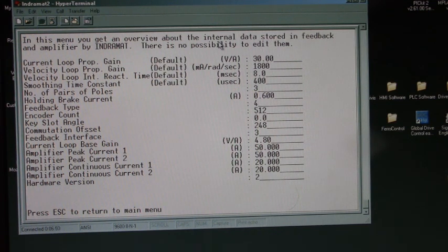But if you've got a good motor, don't separate the two, because it would be a lot of fun trying to put that back together properly timed. And if you didn't have a drive and a bus power supply and the cabling, it would be near impossible, because you have to be able to verify your position is correct by running that motor. So don't do it unless you absolutely have to.